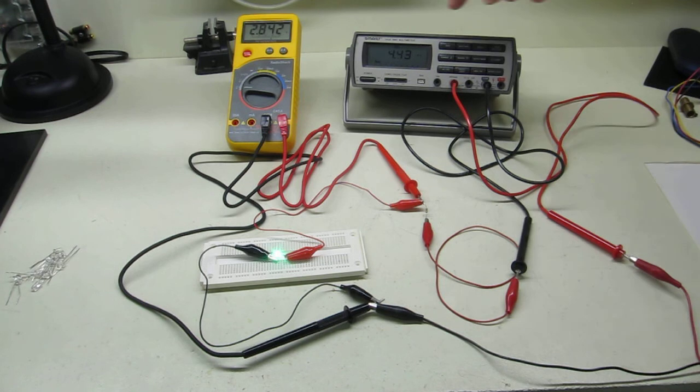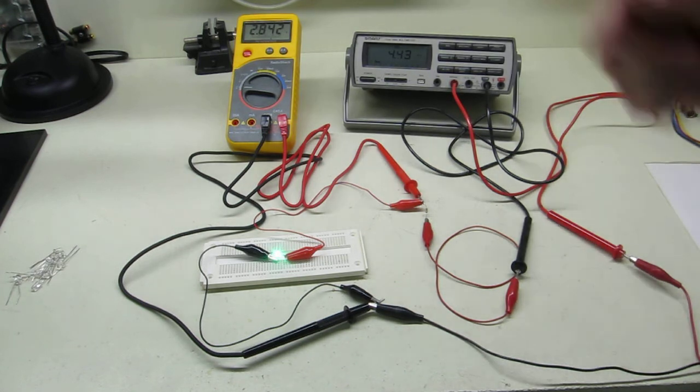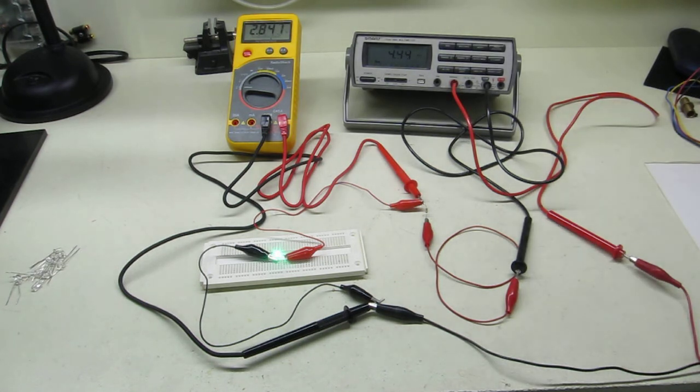Now, as the current increases, the voltage also increases across the LED device. This isn't necessarily true with an ideal diode. With an ideal diode, no matter what the current is, we expect the voltage to be about the same. But for a real device, there are electrical resistances within the device itself which lead to this characteristic curve. And in a few moments, we'll look at how to analyze that.